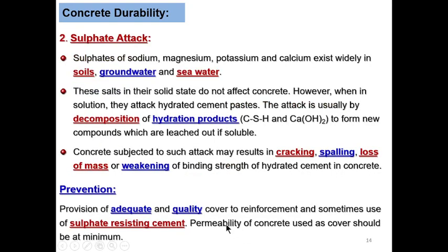So let's look at another durability challenge, sulfate attack. We have sulfates of sodium, sulfate of magnesium, and potassium and calcium. They exist widely in soil, they exist in groundwater, and they exist in seawater. Now, these salts in their solid state do not affect concrete. However, when in solution, they attack hydrated cement paste. The attack is usually by decomposition of hydration products.